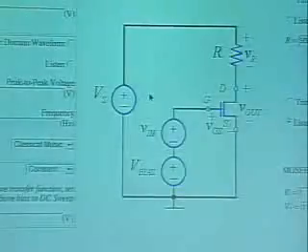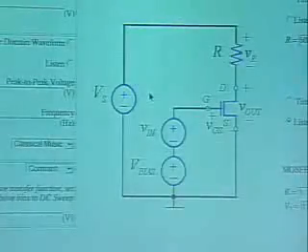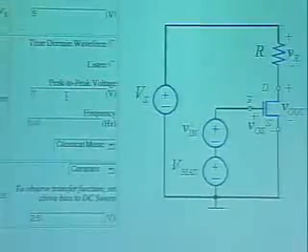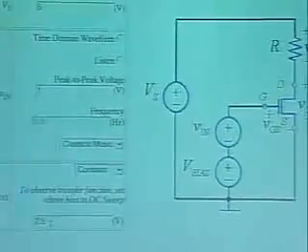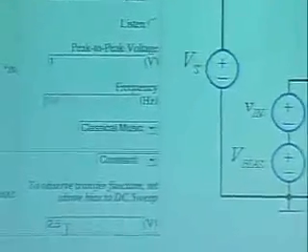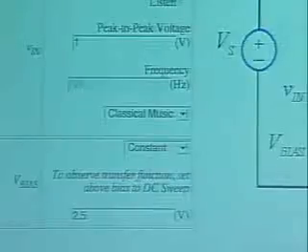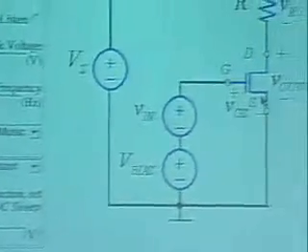Lots of distortion, right? So as you can see, there's a bunch of distortion, and that's as you expect because the peak-to-peak voltage is 1 volt, the bias is 2.5, and so this is clipping at the lower end, plus the MOSFET is nonlinear. Okay, so you can play around with a bunch of things, and you can have a lot of fun.